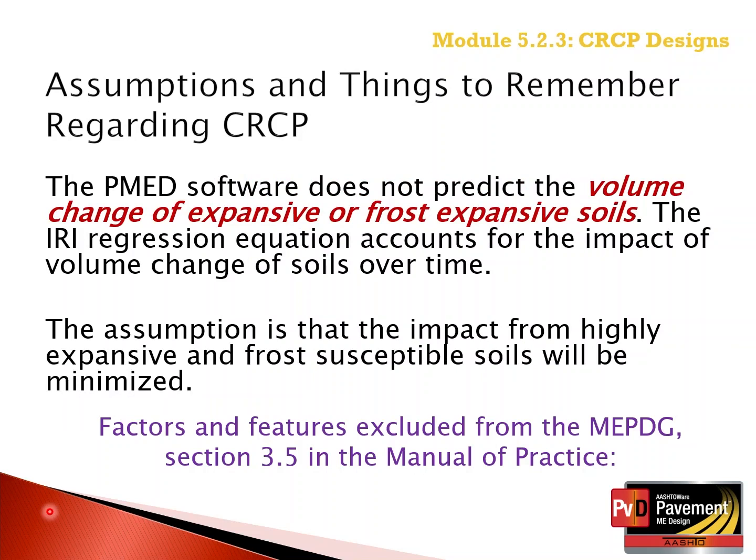As mentioned in the MEPDG Manual of Practice, also under Chapter 3.5, Factors and Features excluded from the MEPDG, volume change of the soil in terms of frost heave and/or frost susceptible soils, or potential vertical rise from expansive soils, is not predicted by the software. It is assumed that the subgrade will be properly treated and constructed so the volume change of the soil is minimized and does not become an issue throughout the design life of the CRCP.